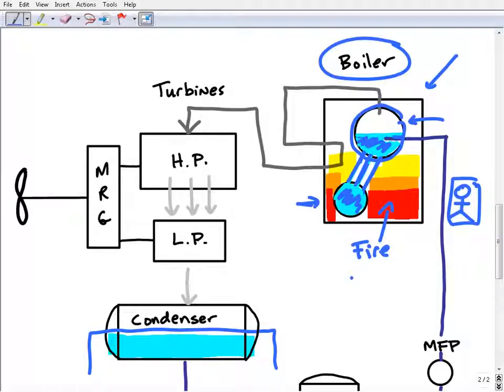DFM, diesel fuel marine. They can even use JP5, which is like jet fuel, but that's not so common. You're going to use some sort of marine fuel, and I don't want to go too much into the boiler, but essentially that fuel gets atomized, sprayed into the boiler, and there's a heat source, and that fire just gets going. Think of it as a massive furnace that's producing intense heat. So that's pretty much how we fuel the fire for the boiler. We're using some sort of diesel fuel marine type of thing.